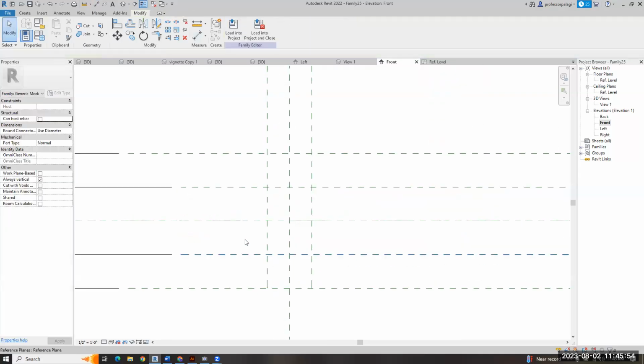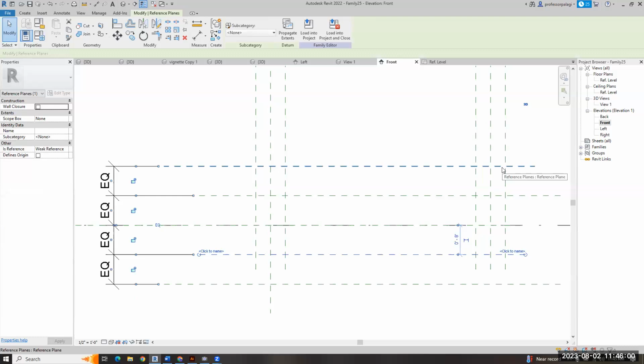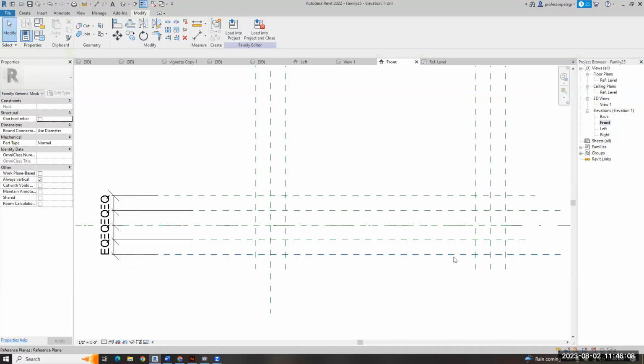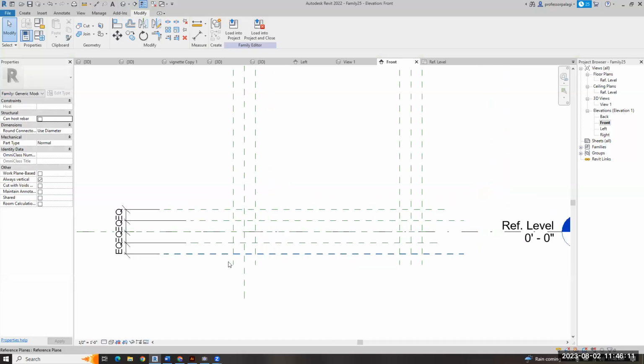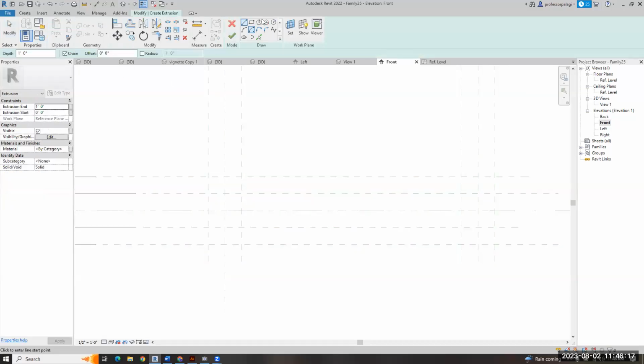Equal. I can grab this one that's next to the pin one and say, let's do 8 inches. Yeah, nah, it's a little much. Let's do 4 inches. I don't think the proportions are that much. There we go. That looks more like that bracket that we see in the thing. Okay. So now we're looking from this side and we're just gonna do a whole bunch of extrusions. Real simple thing, create extrusion.